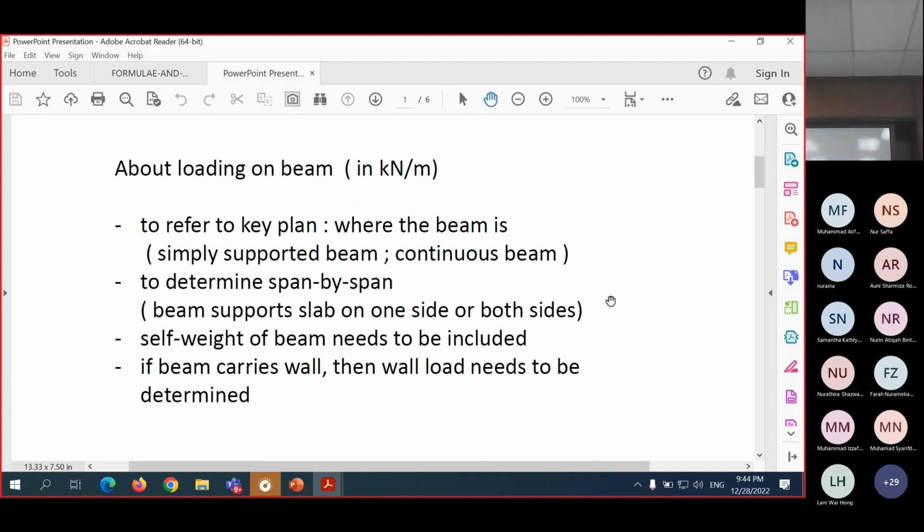Then, when you calculate beam loading, you have permanent load. Okay, permanent load, if it is given to you and indicated without self-weight, then for the beam you have to consider the self-weight. Sometimes the permanent load is given by indicating this is without considering self-weight. So permanent load can come from finishes and other sources. If it is indicated without considering self-weight of the beam, then one of the permanent loads that you need to consider is self-weight of the beam.